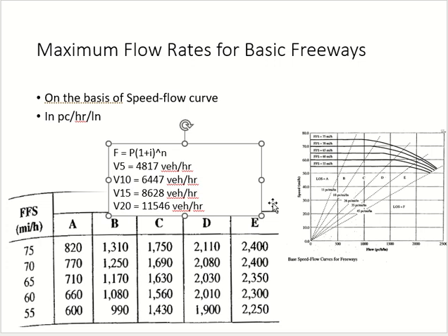Okay, so these are two differences. The third difference is what? There is another difference. You cannot see it properly here, but what was I calling this? Flow rate. And what are these values? Volumes. So again, you cannot compare flow rate with volume. To compare the values which I have to the values in the table to know the level of service, I have to take care of three things: converting vehicles to passenger cars, converting volume to flow rate, and converting the total to per day.